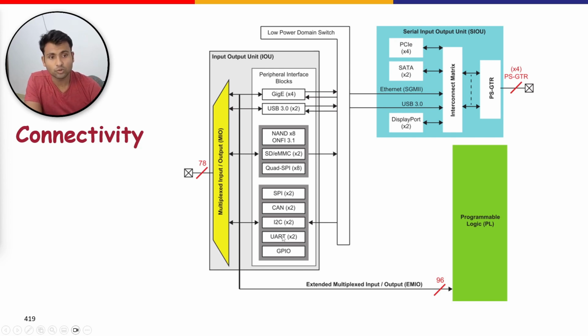The UART IO interface, it is 2 in number, and it stands for Universal Asynchronous Receiver Transmitter, which is used for low rate data modem interfaces, and it is used for serial communication. It often is used for terminal connections to a host PC. The SPI, that is also 2 in number, and it's a standard for serial communication, and it is based on a 4-pin interface and can be used either in master or slave mode.